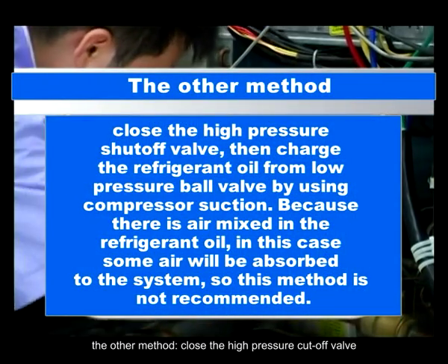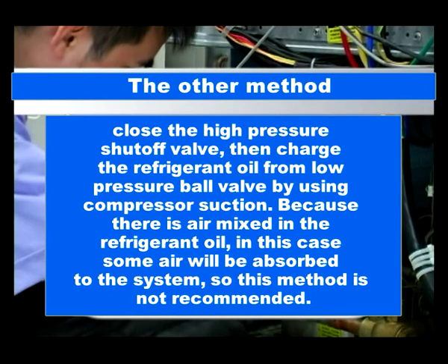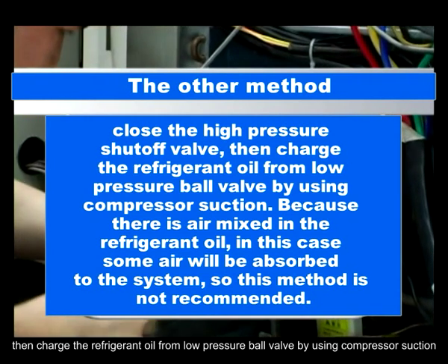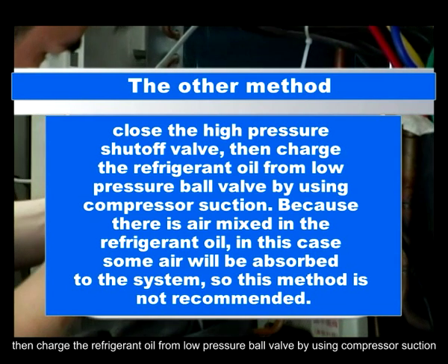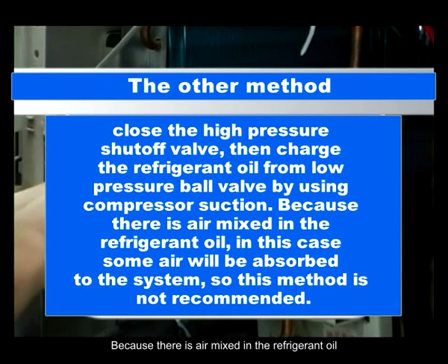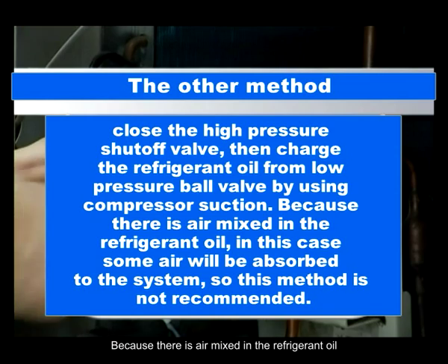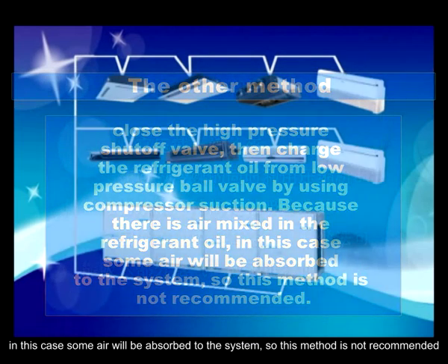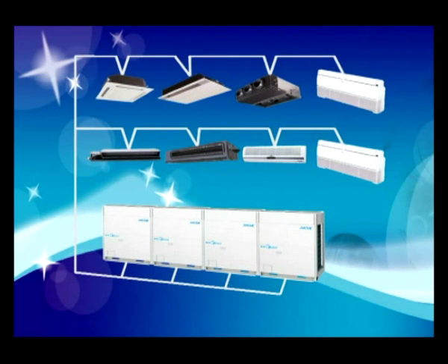The other method: close the high-pressure cutoff valve, then charge the refrigerant oil from the low-pressure ball valve by using compressor suction. Because there is air mixed in the refrigerant oil, some air will be absorbed into the system in this case, so this method is not recommended.